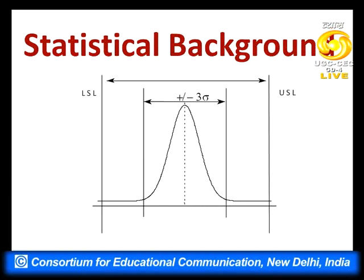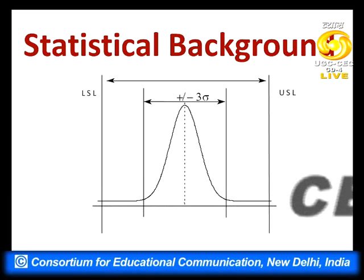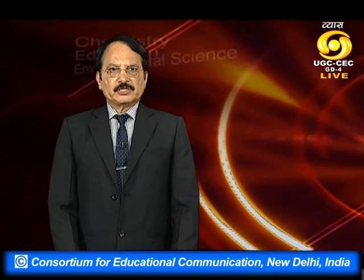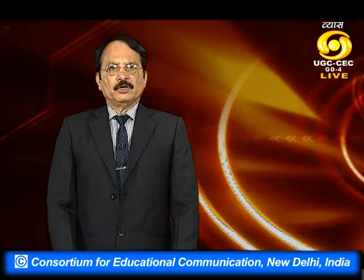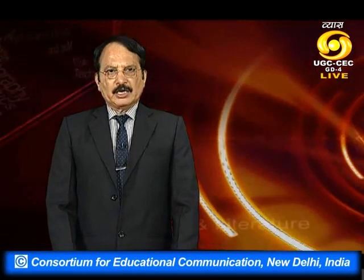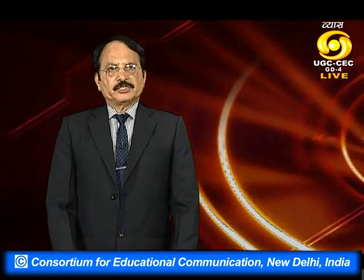And now I have specified the lower specified limit as well as the upper specified limit on this graph. These limits are given by the customer, and the process limits are given by the plus minus 3 sigma limits. Now, the lower specified limit and upper specified limit cover plus minus 6 sigma, whereas the process covers only plus minus 3 sigma.